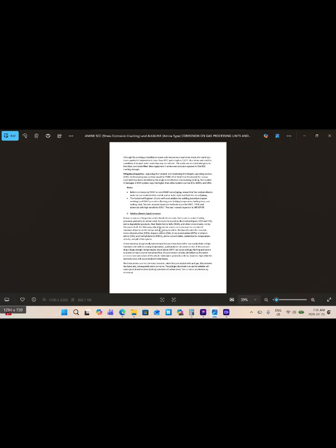Alkaline amine type corrosion: we have it. This is another type of damage that could happen in an amine system, but this is not a cracking type. This is corrosion. Amine corrosion is generally a localized corrosion, not a general corrosion, and it occurs in the amine treating process and affects carbon steel. The corrosion is caused by dissolved acid gases like CO2 and H2S. CO2 and H2S at a certain temperature penetrate the carbon steel,